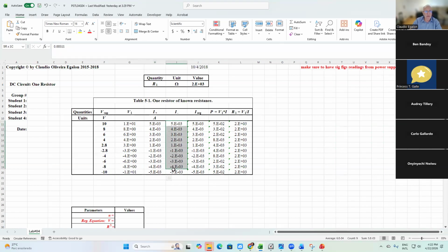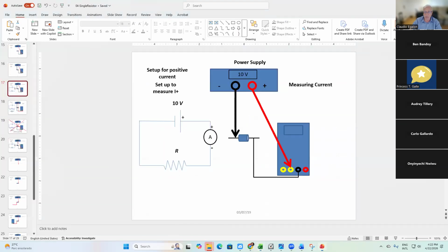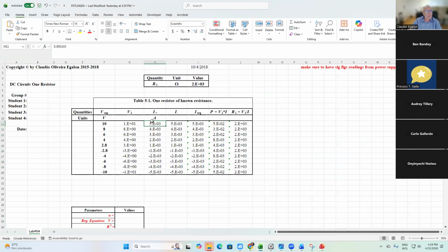What we have here is just the same measurement, but a different spot. I always tell my students to put the ammeter on the other side here so they can verify that the current is the same for this specific circuit. Compare this measurement with this one here. They're very close to each other. They're not exactly the same, but less than 1% difference.